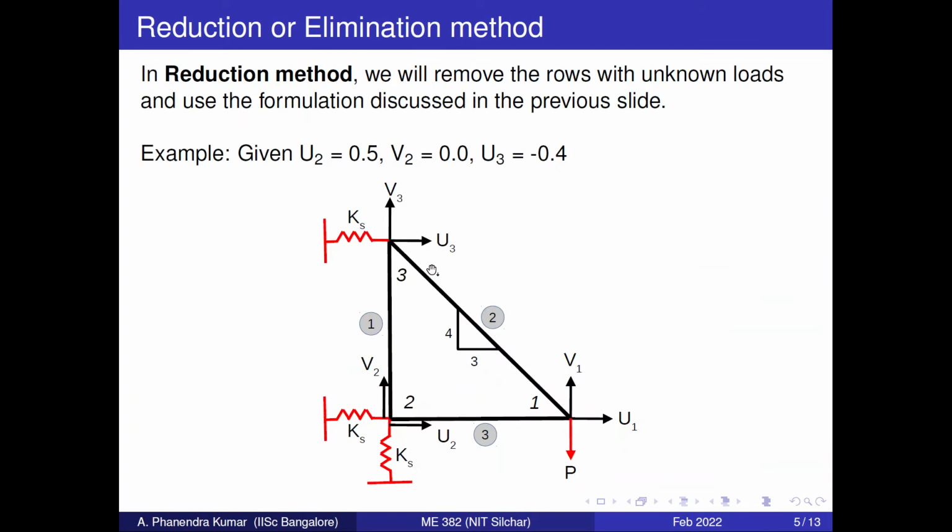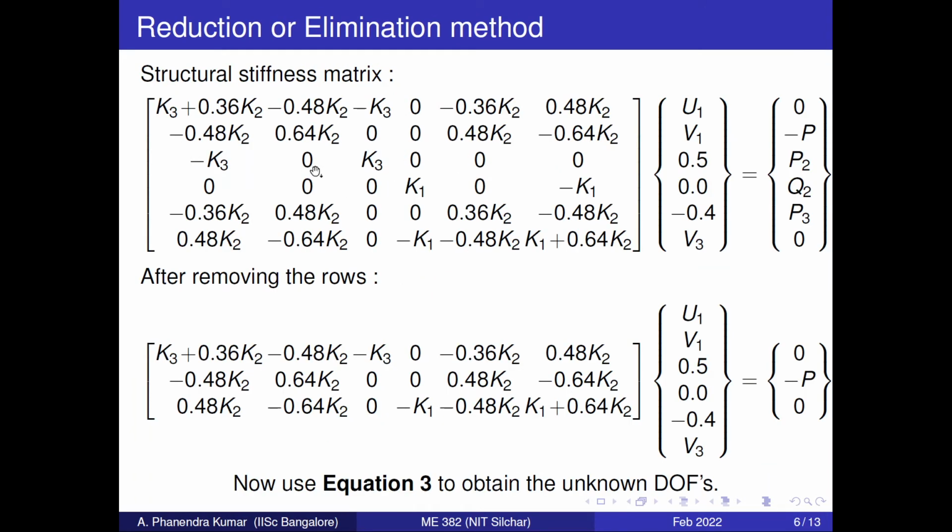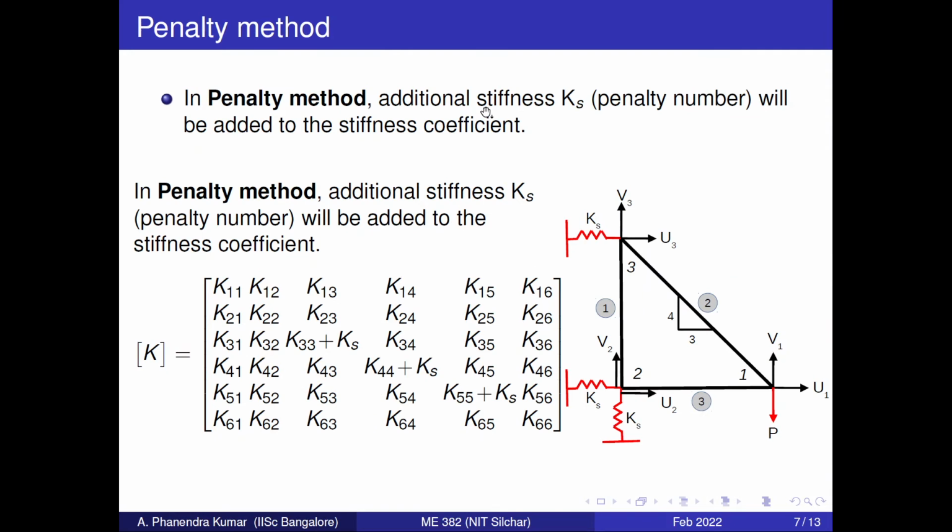So the stiffness matrix will be the same. There won't be any change in the stiffness matrix. We'll use the C square, Cs terms which we have used previously. The same things we are going to use, and we find the final structural stiffness matrix using the combinations of u1, v1, the combination which you have seen in the previous module where we have seen one example.